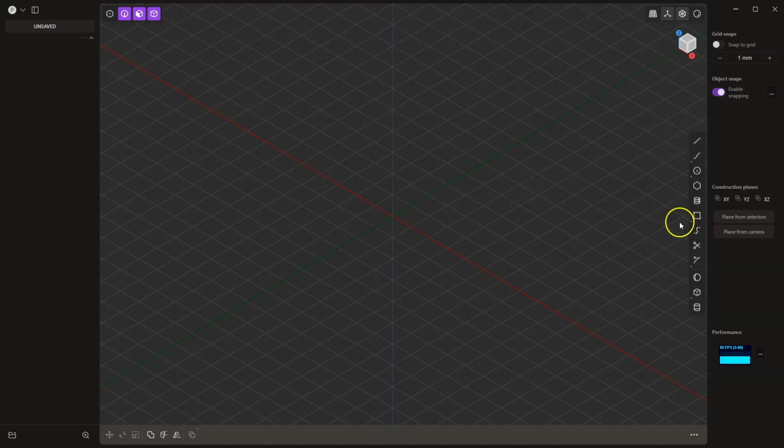Now, as for selecting geometries to draw, as you can see there are small arrows next to some commands, which means that there are additional hidden commands here. To activate the additional commands, just hover the cursor over that command and press and hold the left mouse button. Here we have additional commands that we can choose from. How to select such a command from this list? Hover over it, hold it, and then hover the cursor over the selected command. Release the left mouse button, and that command is active. So, as you can see, at first glance it may not be obvious, but we can easily select these commands. Now, if I have an active command, I press escape, and that command has already been cancelled.